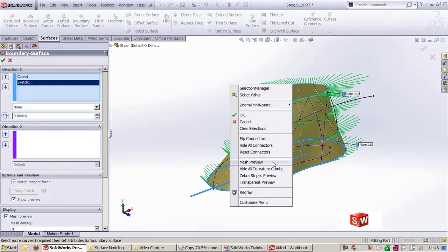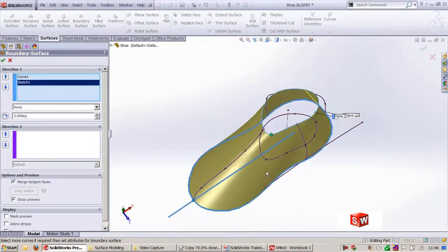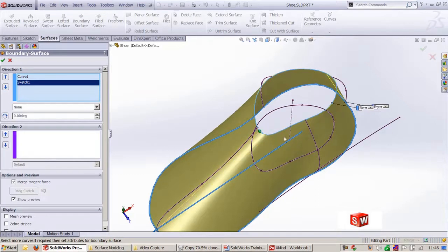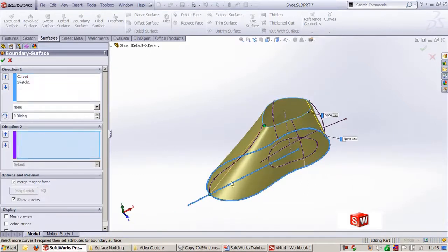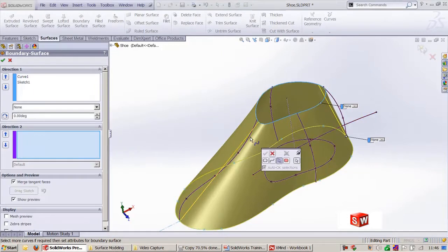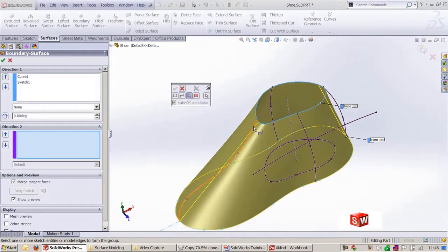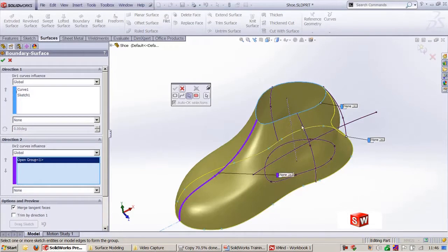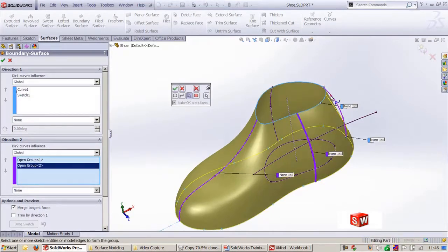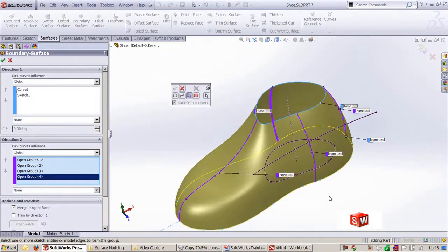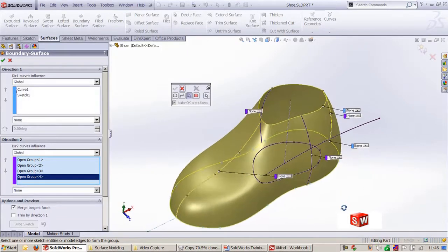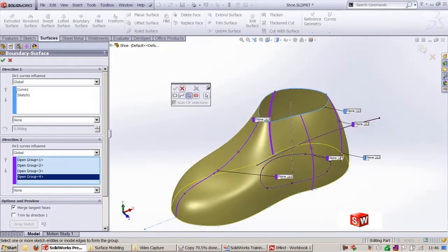I don't require all this zebra lines and different curvature. I will clear the mist faces, and now I can drag this to get exact finishing. And once you completed, you can define the direction too. First one is this. Since it is done in one single sketch, I will use selection bar to say one, open the sketch, okay, and second this one, okay, this one, okay, and the last one. Completed. Now you can choose either it should be normal or it should be tangent.